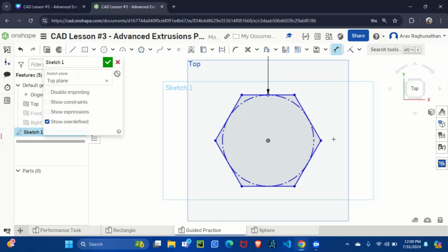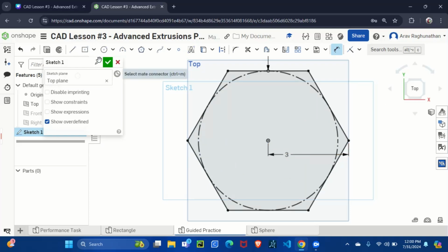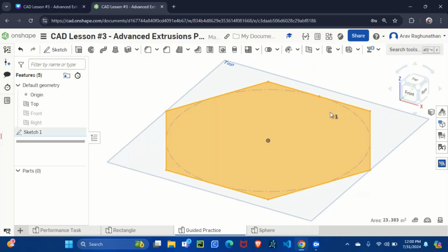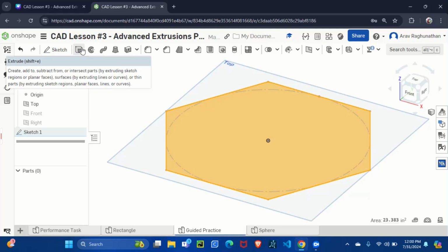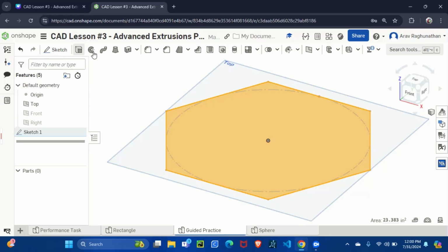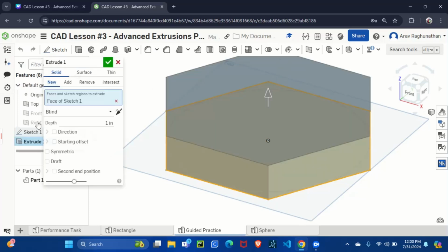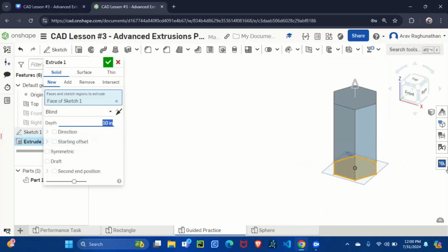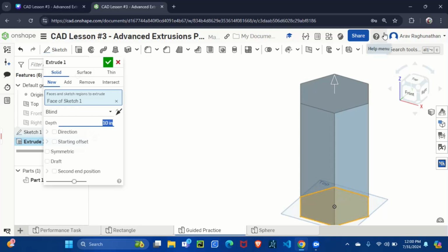So let's also adjust this radial distance. I want it to be 2 or 3. Make it 3. So now 3 is a little bit bigger. Looks really nice. And so now we're going to have to create our main cup. So let's create our extrusion, just the basic extrusion here, and let's say we want it to be 10 inches tall. Now it's starting to look like a cup. All right,